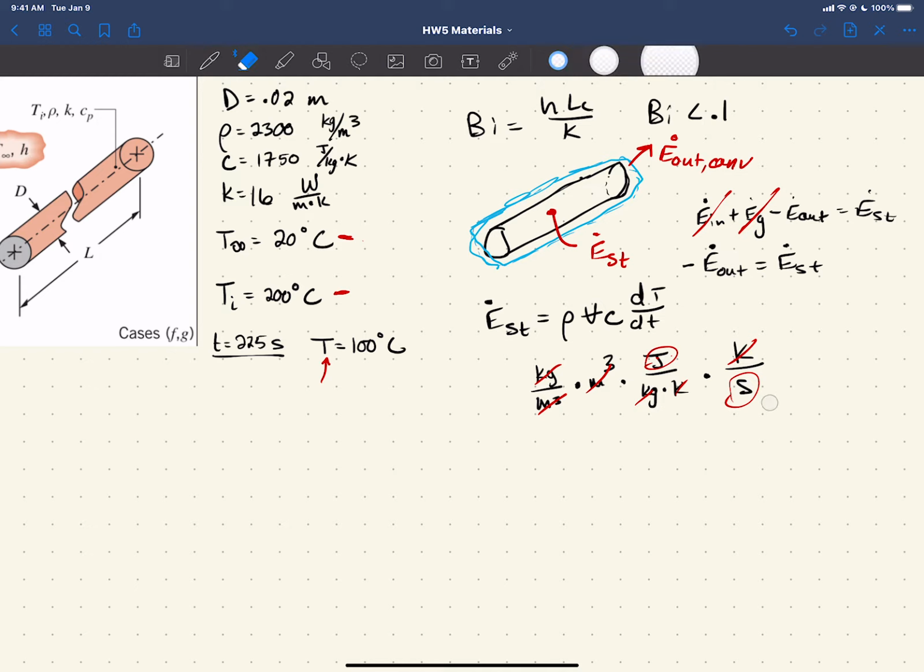In heat transfer we're pretty much always talking about watts. Or you could just remember that these E's have dots on them because they're energy flowing and moving over time, so it's joules per second because that dot tells you it's a time derivative, with seconds on the bottom. However you want to look at it, that's a handy trick if you forget.